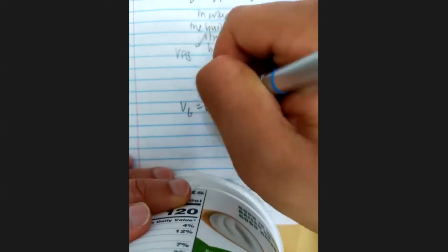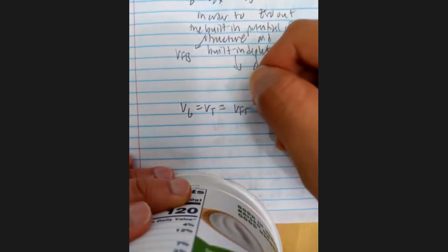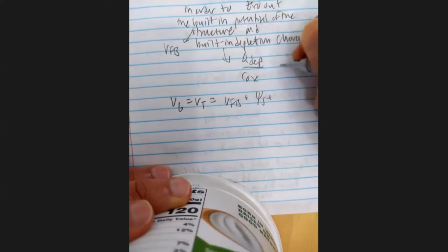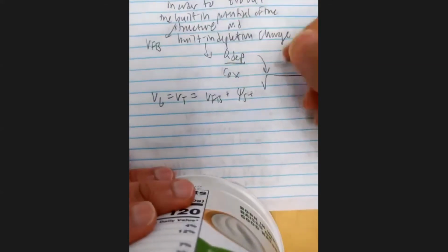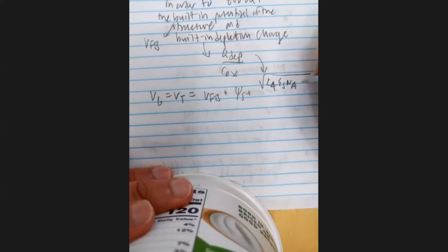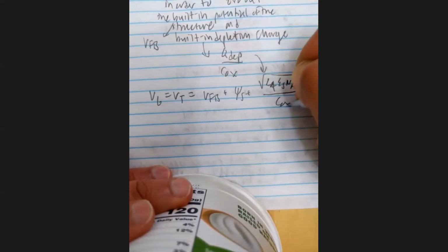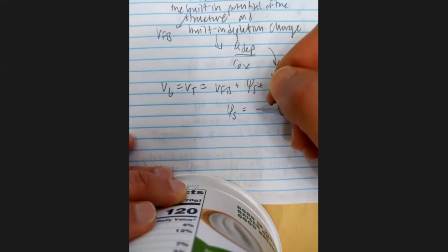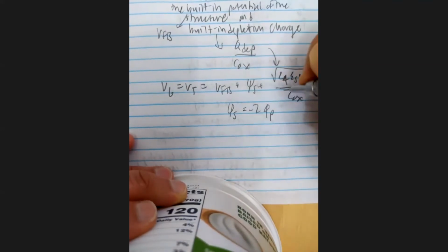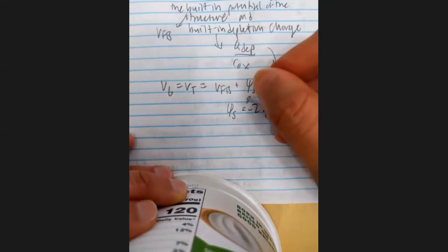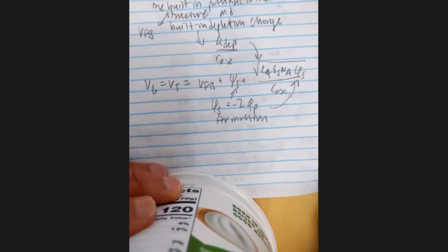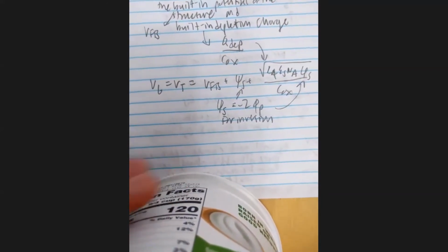And so the final expression is that Vg, which is going to be equal to Vt in this case, is going to be VFB plus psi s or phi s, whichever one it is, plus this Q dep, which we saw before is going to be the square root of 2q epsilon s Na times psi s over Cox. And we showed that psi s has to be negative 2 phi p in order for inversion to happen. So we can just plug that in here and here for inversion. And that is the entire derivation done from start to finish, more or less.